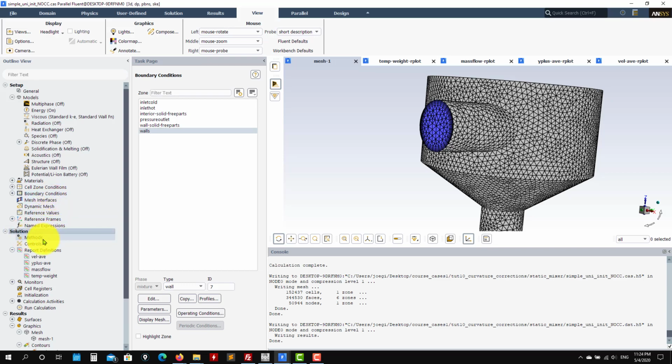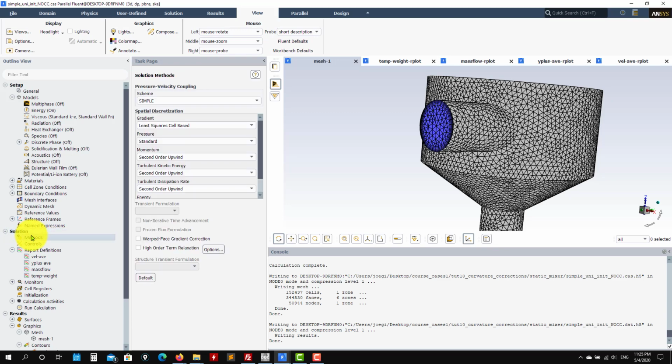And then we go to the tab where we have the solution methods. Here I will show you, because there was a question raised during the lectures, different methods. I will show you a little bit of the behaviors in the different methods. In theory you should get the same solution, but as the methods are different, you will have different convergence rates, so it's quite difficult to assess everything. I have been telling you that probably the coupled version is the best one, but sometimes it's not, because coupled can be really expensive. The cost per iteration is really high, so sometimes SIMPLE is better.